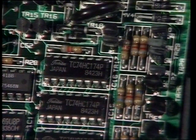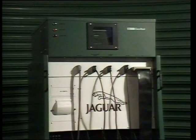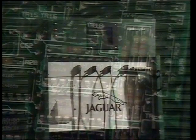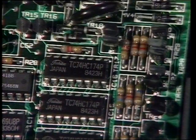Transistors and other such electronic devices are used extensively in Jaguar circuits. Therefore, the use of test lamps to detect faults is prohibited. The Jaguar Diagnostic System, the JDS, has been designed for circuit testing and fault diagnosis. Don't use any other tools on the electronic circuits in these cars.